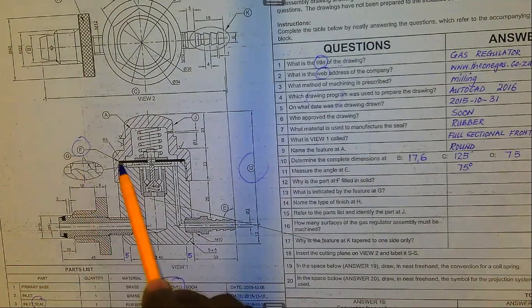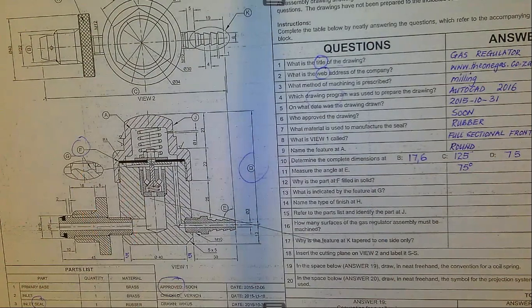Now, you'd find that in most cases, if it is something to do with sealing, that could be rubber, but at some point as well, if it is just placed anywhere without element of sealing, that may relate to a thin material which cannot be shown by normal hatching techniques. But in this case, we have got a gas regulator. So the assumption is that this is rubber, since it is supposed to provide some kind of a seal. And you can even see that one, number 3, says inlet rubber.